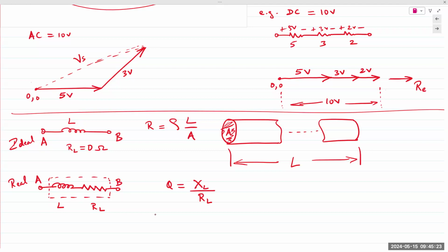In real life, that RL has a value of about 5 or 6 ohms, depending on the construction of the inductor and depending on the application. So for high quality inductors, that is very, very low. In lab 6 in EE 251, we use inductors with low quality on purpose because we want to be able to teach students how to perform these calculations. And so that is what you're doing in lab 6. What you're doing in lab 6 is you're verifying KVL.